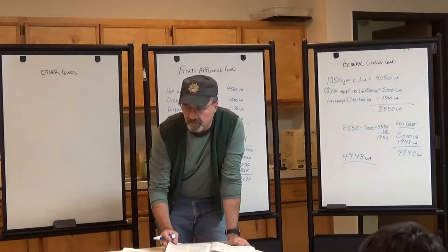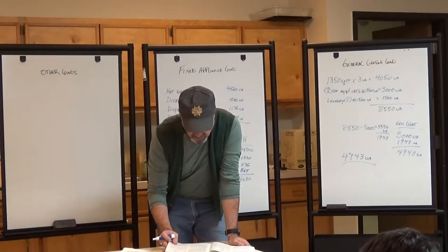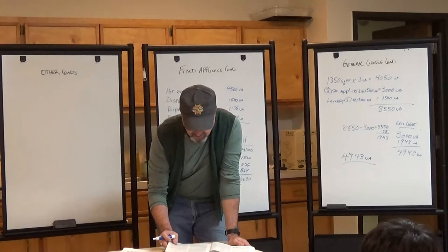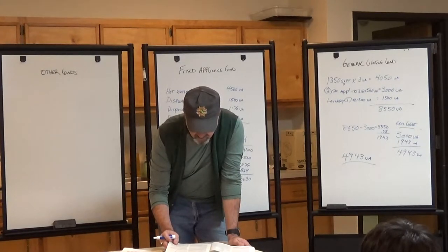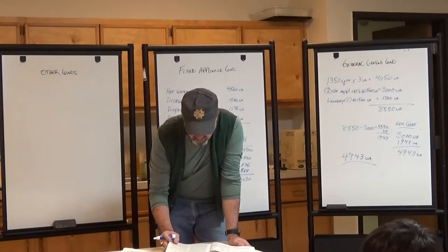Austin, can you read that? 220.53. It shall be permissible to apply a demand factor of 75% to the nameplate rating load of 4 or more appliances fastened in place, other than electric ranges, clothes dryers, space heating equipment, or air conditioning equipment that are served by the same feeder or service in a 1-family, 2-family, or multi-family dwelling.